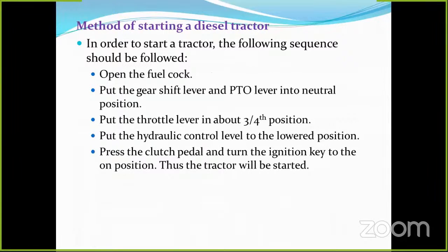Okay, method of starting. It is also one of the procedures, but most people won't follow it. First of all, we should open the fuel cock, then the gear shift lever and PTO lever should be in neutral position, then the throttle valve should be kept at 3/4 position, then the hydraulic control lever should be at lower position, which means the implement should be in lower position, then press the clutch pedal and turn the ignition key.